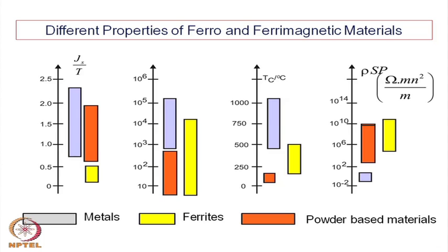There is an insulating, resinous coating on the surface. So, they insulate each laminate from its neighbor, and that is how one increases the overall effective resistance of the system. Otherwise, the eddy current loss will be so high that it will be difficult to design any transformer.